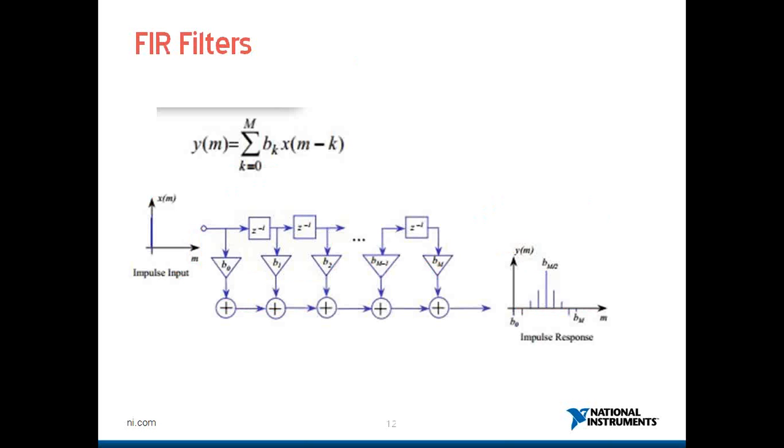So when I talk of an FIR filter, it's defined by the equation which is right in front of you. Now in this equation, if you look carefully, the output, which is y[m], is dependent on the current input and the previous inputs. And each of these inputs is being multiplied by a coefficient and then added. So the dependence is only on the current and the previous inputs.